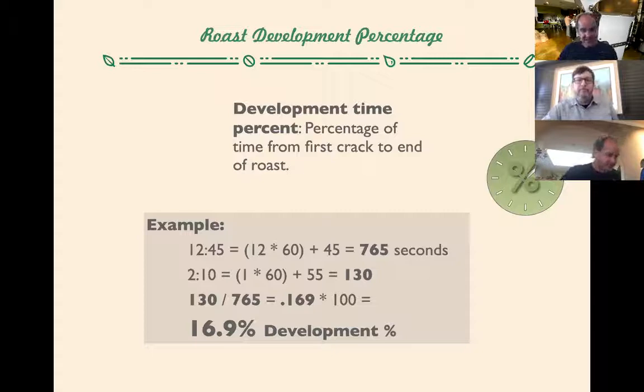At the same time, of course, that doesn't exclude the possibility that, let's say, air pressure could be different in this scenario versus other scenarios where you're roasting, and air pressure changes can occur easily, especially if a roasting machine has been operating for a number of hours, then the air throughput through a machine, because there's more chaff and more debris, can change the heat transfer quite dramatically.